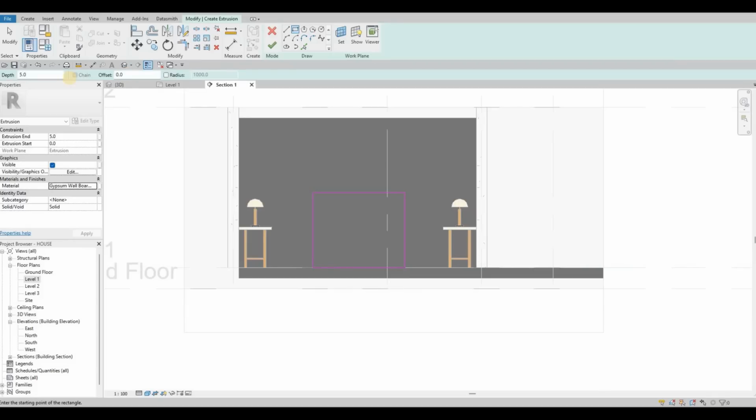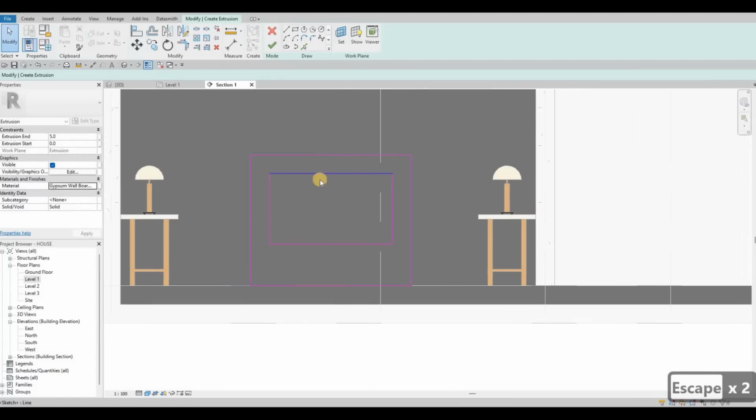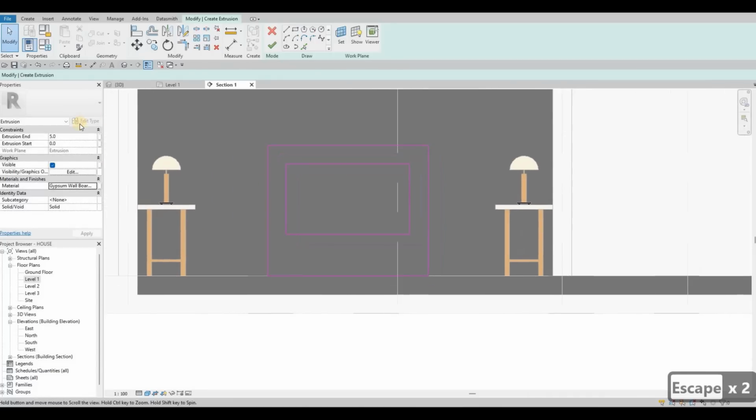And then we're going to offset this 150 probably or more. Now, let's do around 200, spacebar, and then I'm just going to pull it somewhere here. So that's 200 offset, and I'm going to extrude it around 300, and then let's see how it looks.